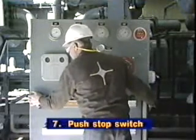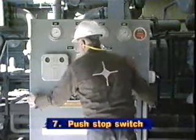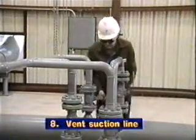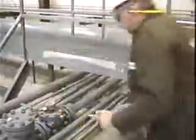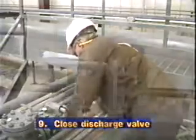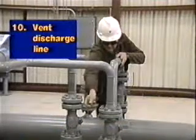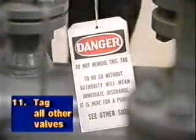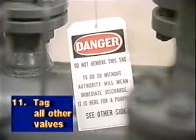Now push the stop switch on the control panel. Your next step is to vent the suction line. Now close the discharge valve and vent the discharge line. Finally, tag all other valves that have been moved from their normal operating position.